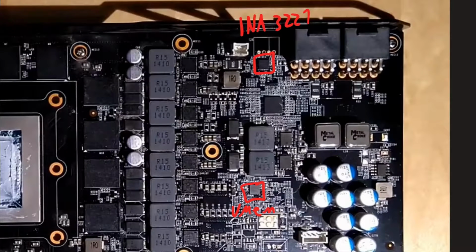The INA3221 monitors the voltage drop that occurs on those shunts right here. That's basically how NVIDIA's power monitoring system works. The INA3221 got replaced for the RTX series. Those use onsemi parts. This one can monitor 3 channels, one for each of those shunts.